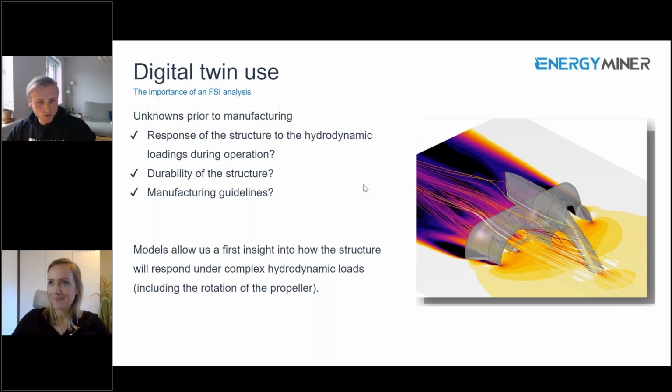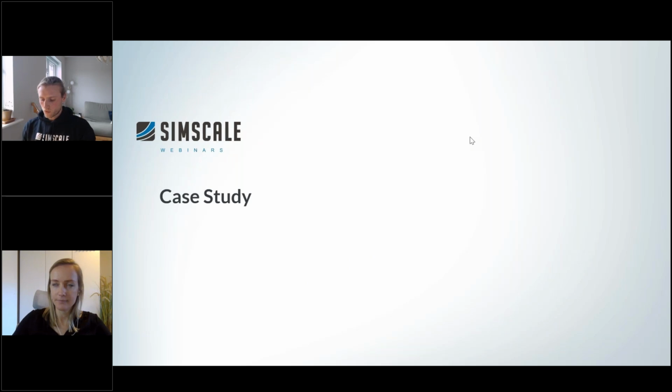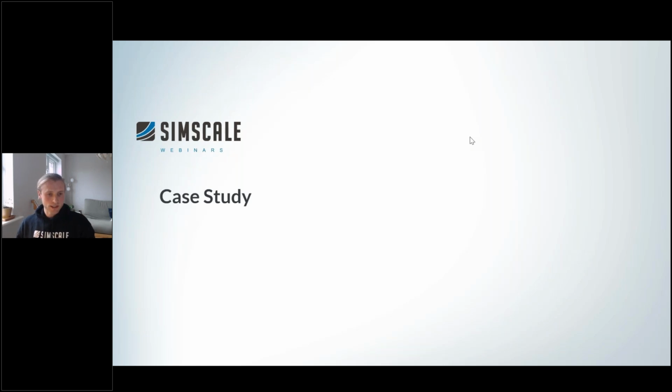So to explain a little bit about what I've been doing with the Energyminer team, it's really leading on from what Chantal described, and actually bringing really complex hydrodynamic loading cases into structural analysis. And the beauty of it is that you do it once with your rotating CFD analysis, and then you can do a lot of optimization off the back of that one analysis in the structural world. So it's a really efficient way to do large design space exploration. And I will present that now.